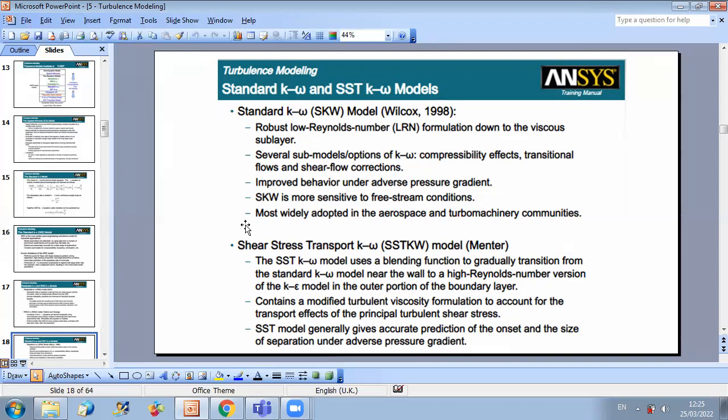So it's the rate at which turbulence kinetic energy is converted into thermal internal energy per unit volume and time. And this omega is related to epsilon through an equation: omega is epsilon over k, times a certain coefficient, and this coefficient is a model constant that also can be determined empirically.